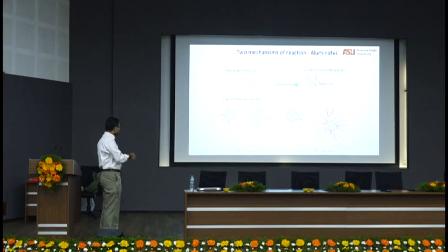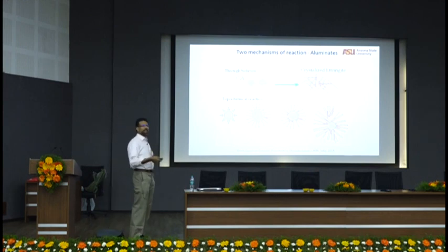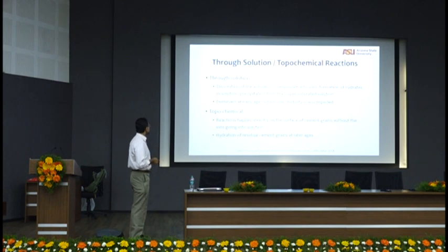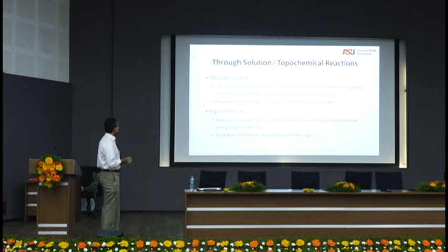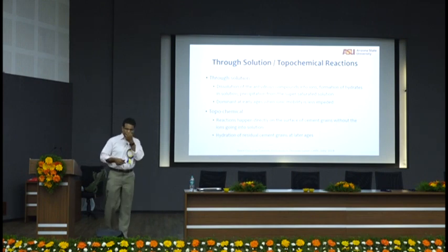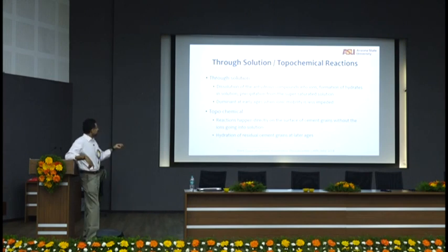Through solution and topochemical. Topochemical is things start forming on the surface. Through solution is things dissolve on the surface and crystallize. So same idea but different ways of doing it. Through solution is what I talked about so far. Anhydrous compounds become ions, hydrates form. Topochemical reaction happens directly on the surface. First one is more common, second one not that common in cements.